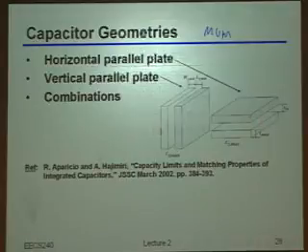Okay, how about in this vertical geometry here? What is it you can actually control, and what is it you can't? And by the way, just to keep things simple for now, let's assume we're going to do everything in this particular example with just one layer of metal. So what is it you can control, and what is it you can't? The length is the only thing you can control. Okay, that's basically correct.